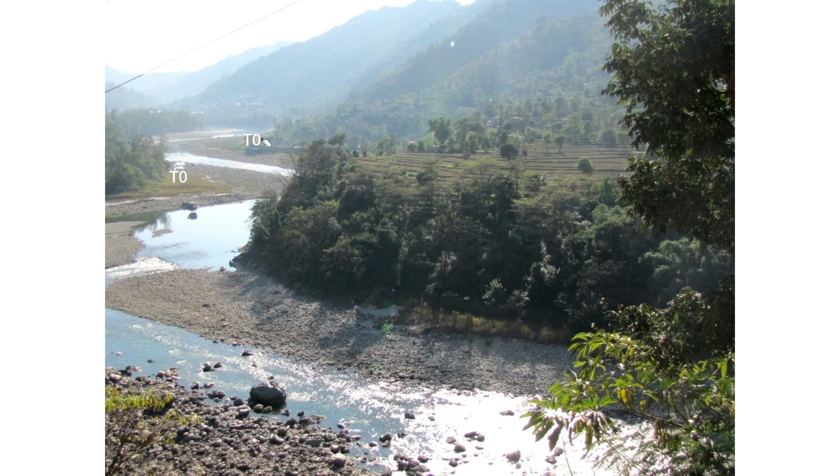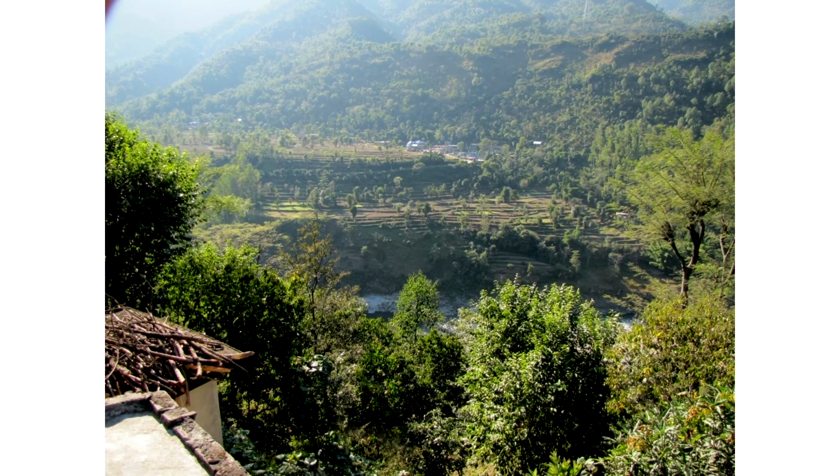So look carefully at this one. We have a slight elevation over here also, and then it goes down. So this is T1, and this is T1, equivalent to this one on either bank, and this is the higher terrace as compared to that. So this is T2. Here you can see the strath, or not strath, but the tread. So you have one going down here, then flat, and then going down, and then finally getting into the channel. There may be one over here actually.